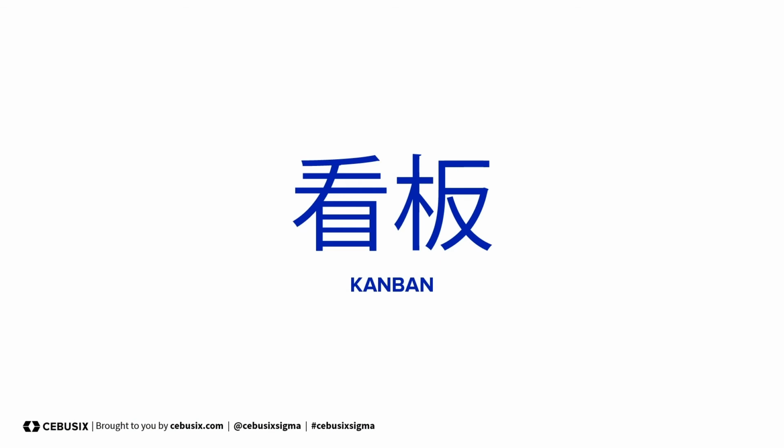Kanban is a scheduling system, and its implementation is an important prerequisite to just in time manufacturing. The word translates to signboard, and it indicates a demand under the pull manufacturing system. Each process issues a request, or Kanban, to its supplier as it consumes a part or product. A process does not consume a part or product without a request. Nothing is transported to or from a process without a request.